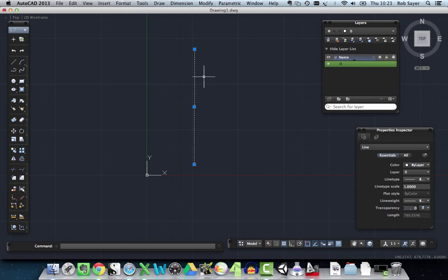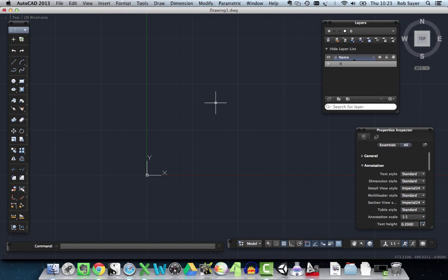We want the equivalent of the old drafting using a set square and a T-square to be able to draw straight up and down. Now, in AutoCAD, that's called Ortho Mode. Down where your model space selection is, where we looked previously, there's lots of little different snaps and items, and in the Mac version it's not totally obvious what each thing does.